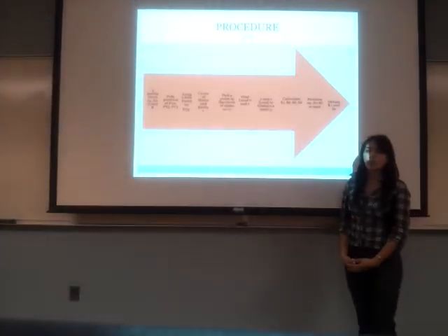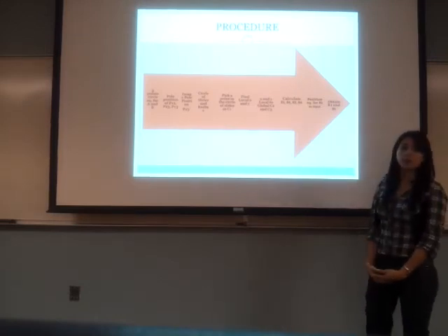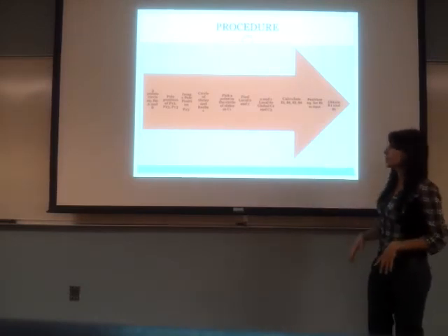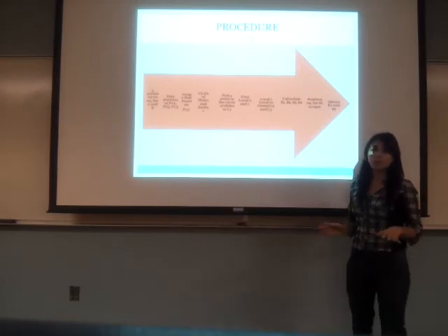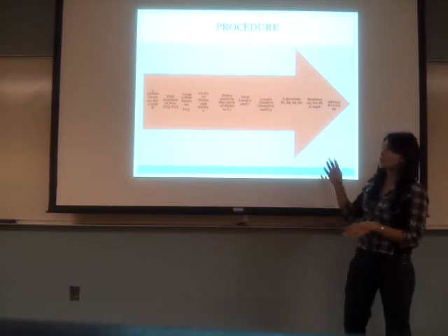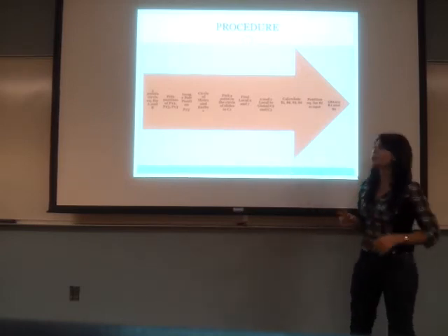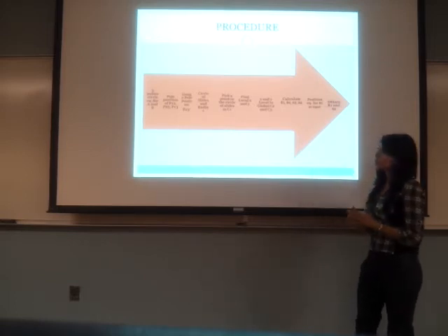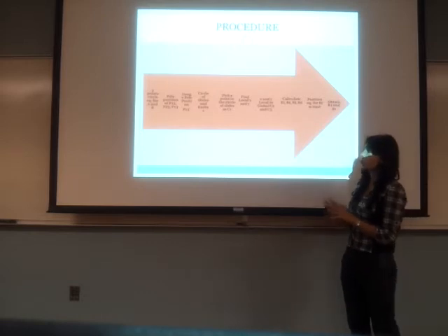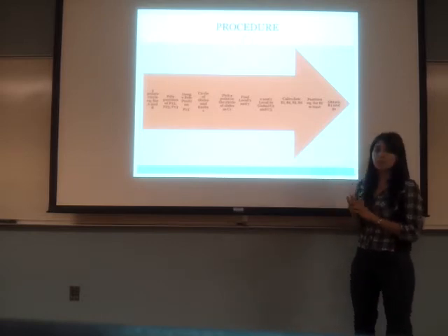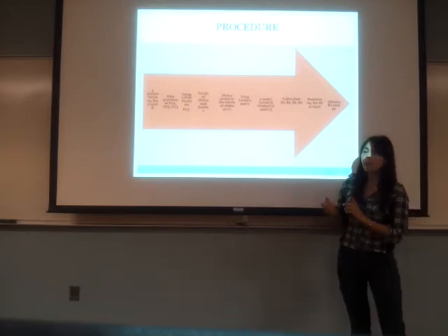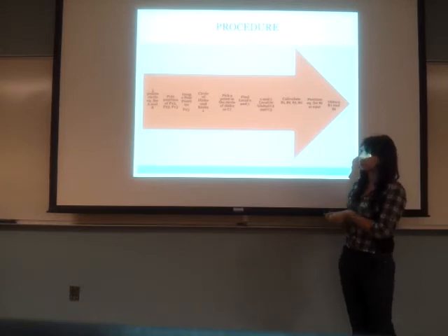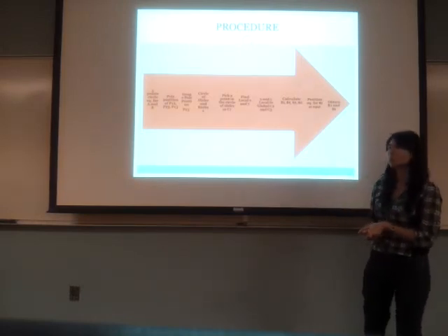The procedures for the synthesis of the slider crank mechanism are a little bit more complicated. First, we got 3 positions for A and B. We did the 3-point circle equation, and that way we found R2 and the length of AB. With that, we found the pole positions P12, P13, and P23. With P23, we were able to find the image pole position, P23 prime.